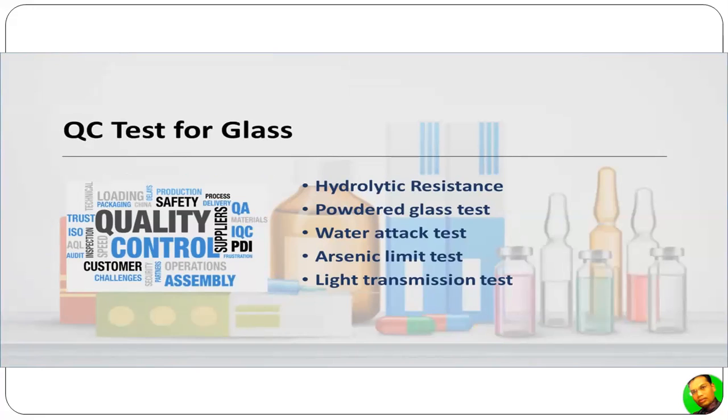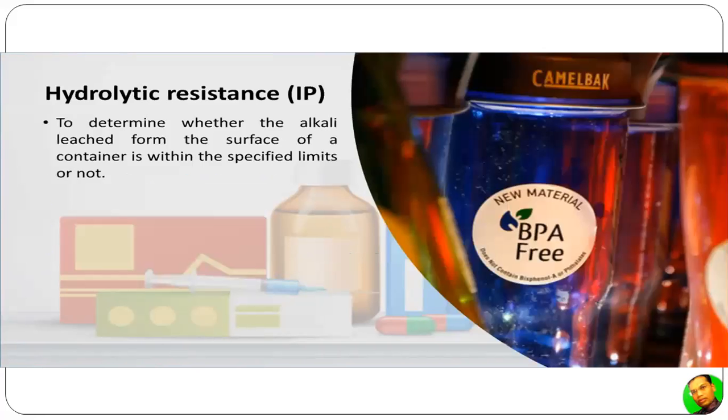So, particularly the tests to be performed in order to assure the quality of the glass material are the hydrolytic resistance test, powdered glass test, water attack test, arsenic limit test, and the light transmission test.